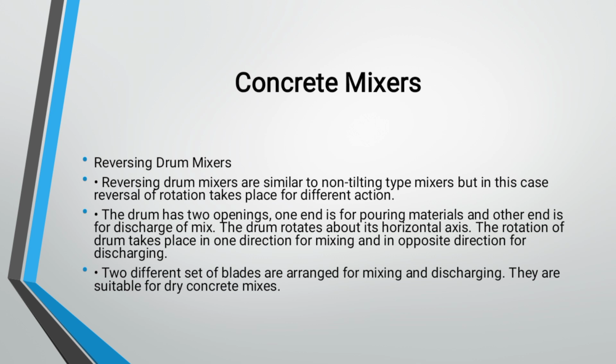The rotation of the drum takes place in one direction for mixing and in the opposite direction for discharging. And it has got two sets of blades arranged for mixing and discharging. They are suitable for dry concrete mixes.